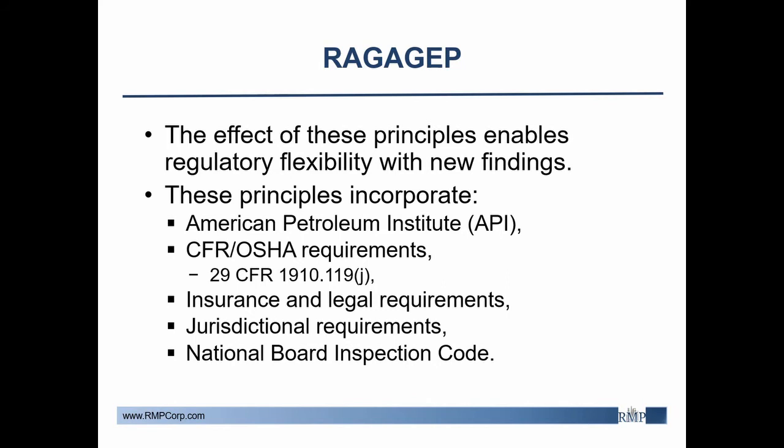It incorporates a service record that should be established after the first inspection on any on-stream methods or external examination. We also see API 510, which covers maintenance and inspection of pressure vessels, API 570 and 576, which are piping inspection codes for repair, alteration, and re-rating, inspection of pressure relief devices as well, and the American Concrete Institute, American Institute of Steel Construction, American National Standards Institute, etc.